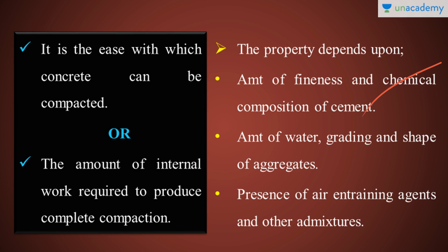Grading of the coarse aggregates also plays a vital role, because there should be proper grading. With proper grading, there will be all kinds of sizes in the perfect proportion, which helps in the reduction of voids. This will help in the reduction of the surface area. So a smaller amount of cement paste is required for wetting all the surfaces, and hence we have extra paste once again, and the workability increases.